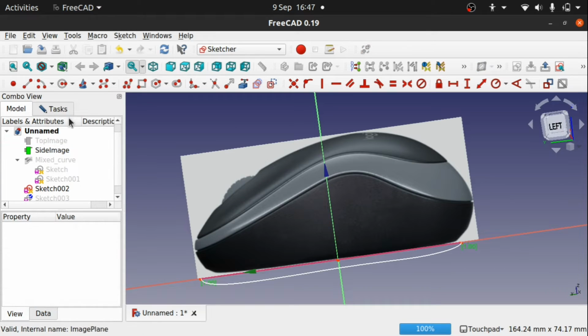So we need some lines, so connect up to that line, and I'm going to come up making sure we get a little red line to say we've vertically constrained. And bring that into there. This time I'm going to connect to that point. So you can connect to the line or connect to the point. I'm going to do the same over here. And come up and connect to that point there.